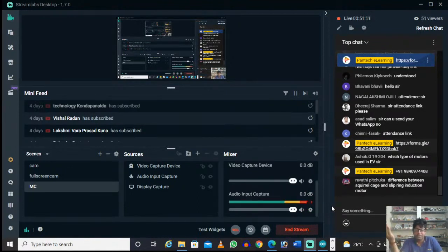And in BLDC machine, what is happening, once we are able to predict the rotor position, at that position only we will apply the voltage, so that the stator rotating flux will be perfectly aligned with the rotor. You will get the better performance. That is the thing.